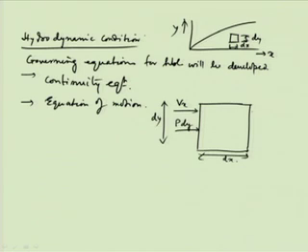Okay. And then on the right hand side it will be Vx plus del Vx by del x into dx. Okay. That will be the velocity here, and the pressure will be P plus del P by del x into dx, into dy, that is the pressure force. So, this is the pressure force, this is the velocity, and that is entering along the x direction and going out along this direction, and now the velocity from the bottom is entering into this layer.